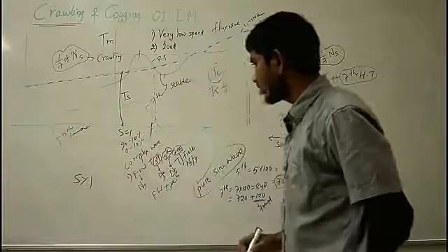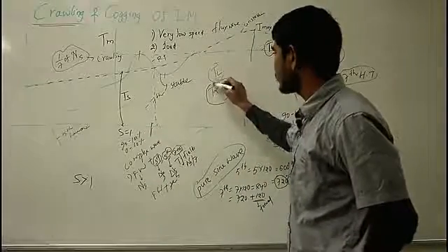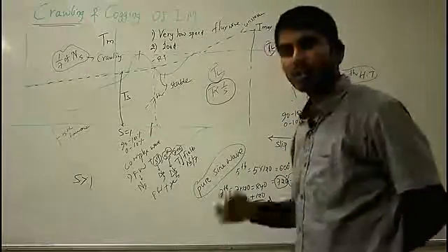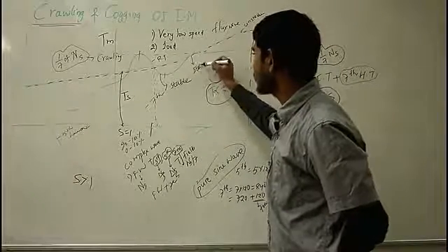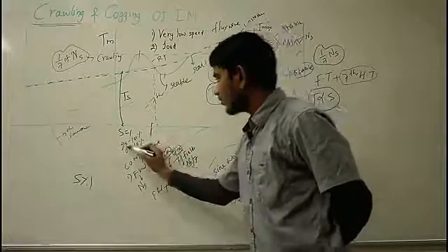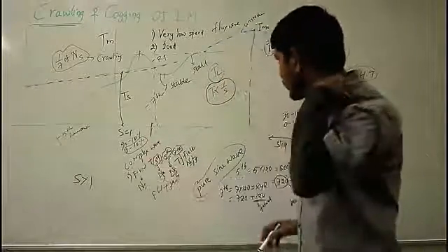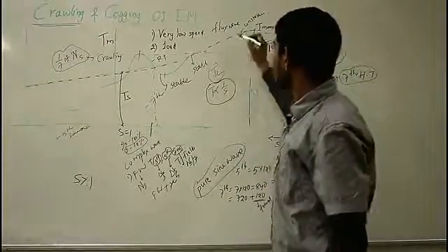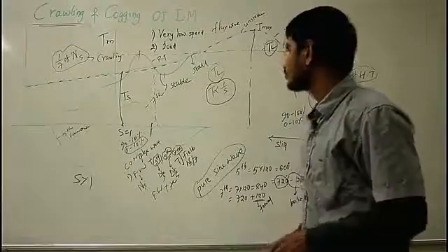So, when you are maintaining the inverse relationship with the torque, the motor tends to stall in this region. The speed is also low, and during the high slip the motor tends to stall, and hence this region is regarded as an unstable region for your induction motor.